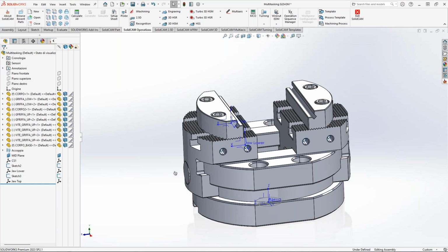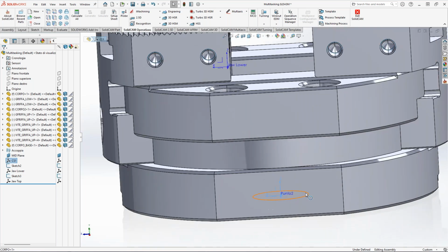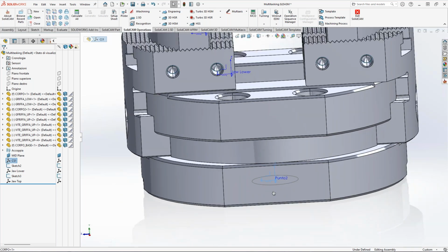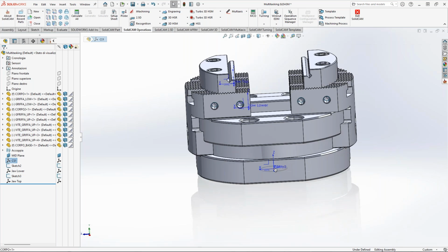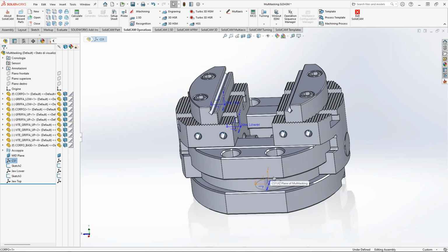The only thing is that whenever you're making the jaws that you want to use with the auto close, it must be done in the XZ plane. That's a current limitation in SolidCAM 2023. And I already predefined the coordinate systems. As you can see, it's nothing so specific. The very first coordinate system of my base is going to be here, and X is in this direction. It doesn't have to be, it can be in any direction. The first of the base is not relevant.